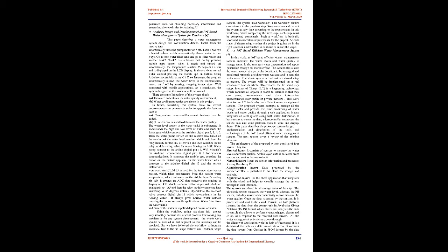Pressing the button on the mobile app sends the instruction to the water heater, which connects to Arduino digital pin 13. An LM35 is used as the temperature sensor in this project, which reads the current water temperature and connects to the Arduino board's analog pin A0.